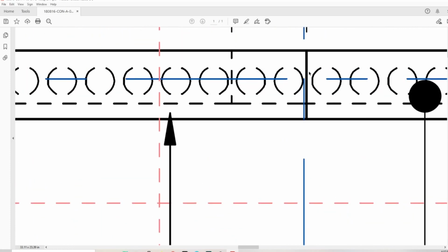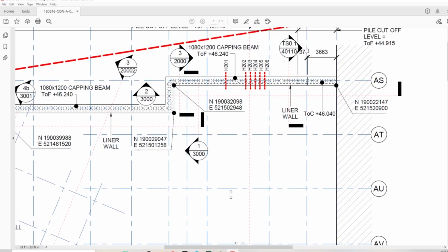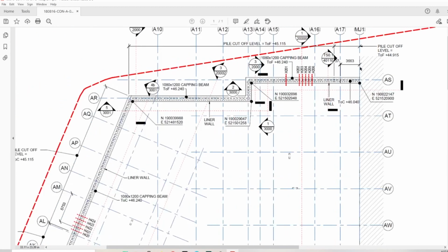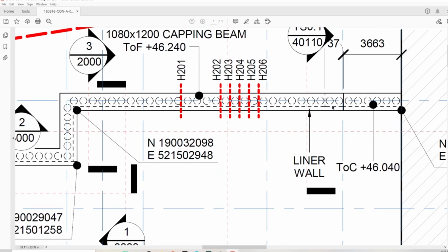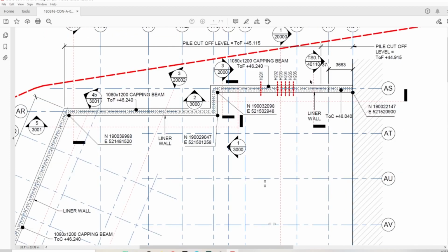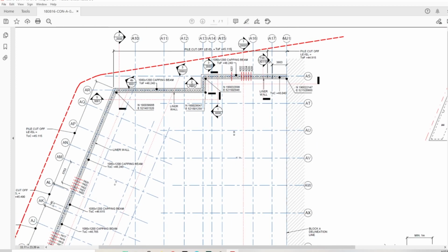An actual change in the beam, on the top of the beam, is here. So you can see here we've got the dimension of the grid line MJ1, we've got the dimension to the step, while we don't have a dimension to this one. So that's going to be typically, as that section showed, 2 piles, but we're going to try to get this information maybe even from the CAD drawing, or we're just going to go by that typical section. So guys, I would say the drawing is quite alright.